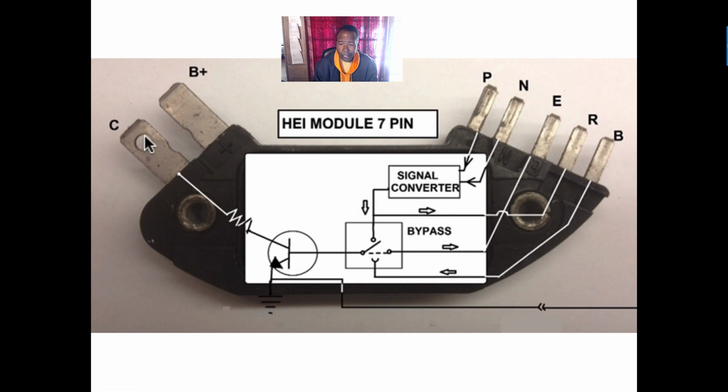But once the car starts, once the PCM sees an RPM right here, this is my RPM signal. Going back to this, letting the computer know, it's a purple wire on GMs, and letting the computer know that the car is cranking. So we're going to send a 5-volt bypass out to here, and now we're going to switch from cranking mode to bypass mode. I'm going to switch this connector like a relay. So now the PCM is going to control the timing through the EST circuit.